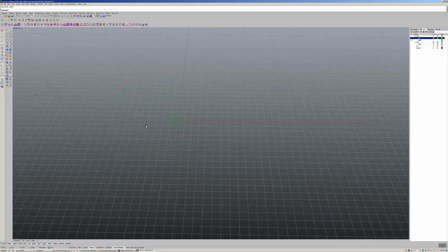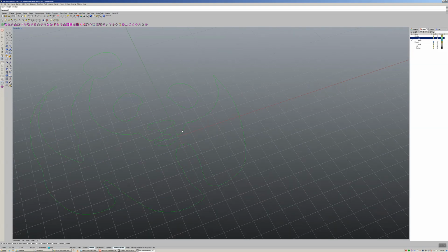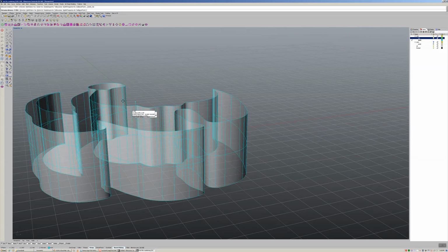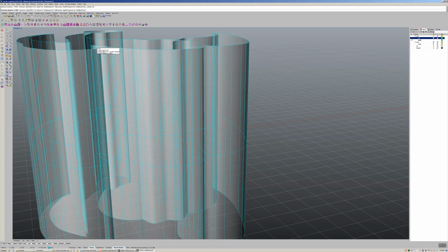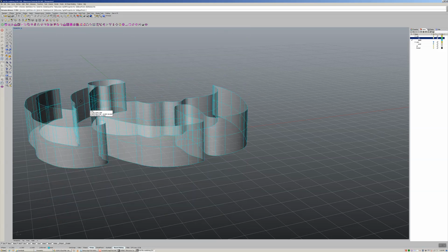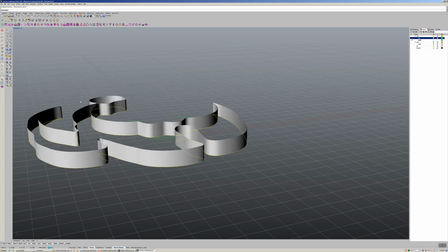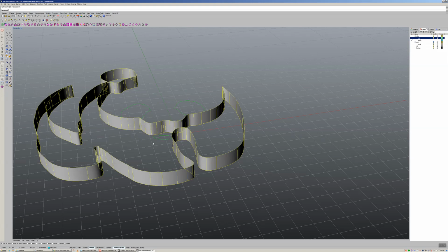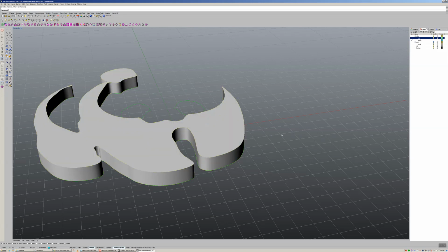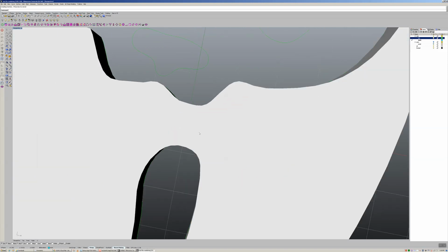Okay, so now we had the extrude surface command. So you select the curve, go under surface, go down to extrude curve straight. And right now it's going which direction, guys? Both sides. We don't want that. We want one side, so we're going to turn that off. Let's go back to, let's say, 1 millimeter. Okay, we have 1 millimeter. And it didn't cap it. So we're going to select the surface, Control C, and now that caps it. But the chin, if you see, the chin didn't get cut out. It's there.